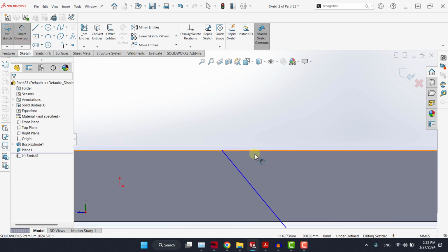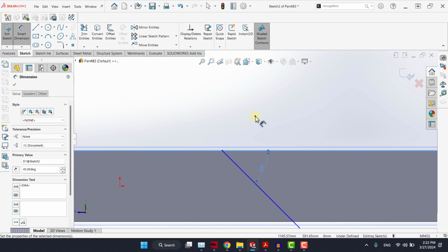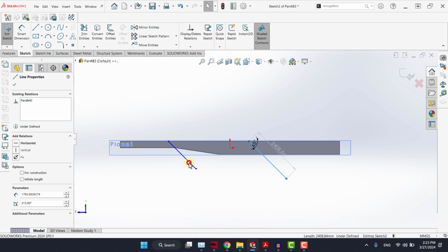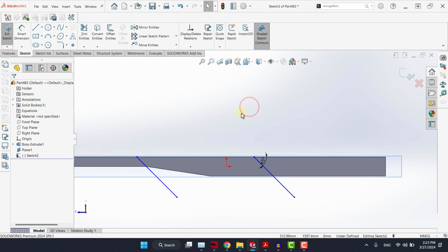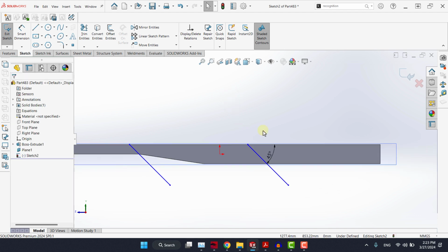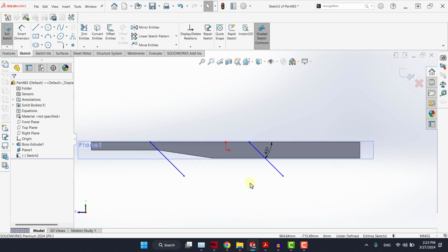After that, I need to make sure that this angle here is 45. Now, at this point, you should think in terms of welding. And before doing so, let's make these equal. So instead of having a vertical weld bead here, it's better to have it inclined with some angle, and that will contribute in a good way to reduce the shear force resulting from having a vertical weld bead. So having these two parts joined with this angle will enhance the performance in terms of shear force.